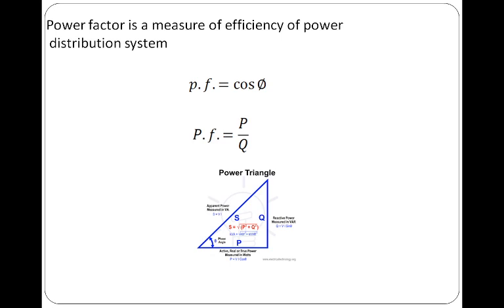But the waste that you cause will not be measured, due to the reactive part of the load. So what is done is they measure your apparent power, then multiply by their own distribution power factor, so this will make them not lose. This is particularly relevant to customers operating highly inductive loads.